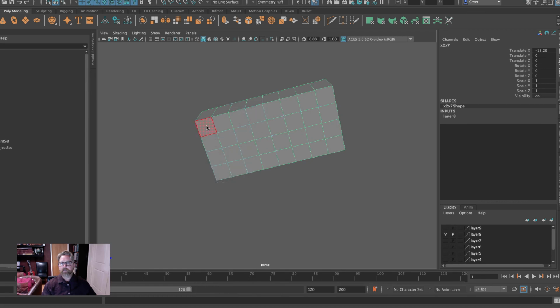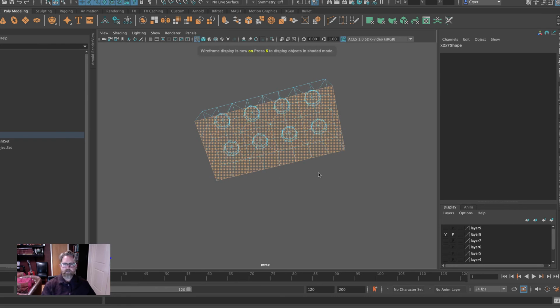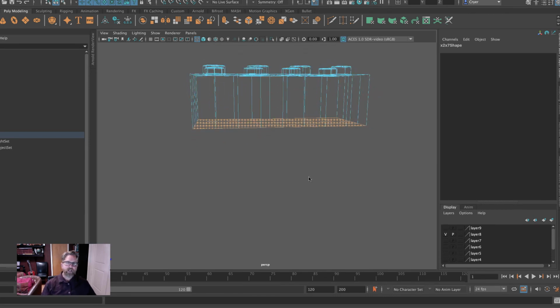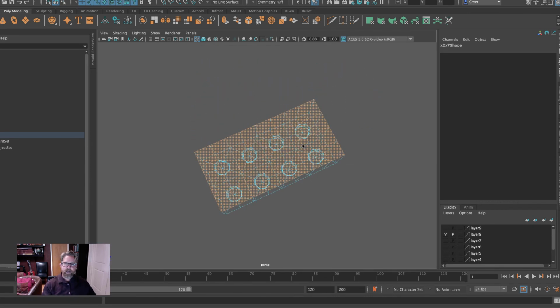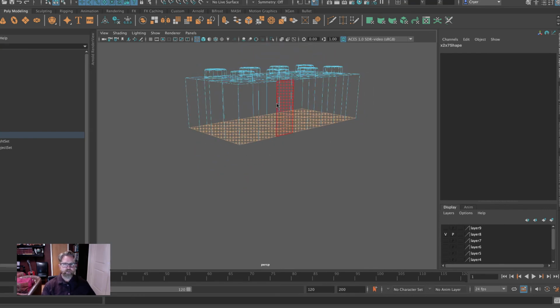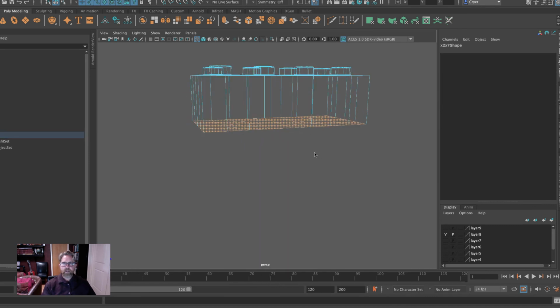We'll right click, we'll shift double click, shift double click, shift click, shift double click, shift click, shift double click. Hit the 4 key and you can see that you've got a clean selection. Another way to make that selection, the more faces you have, that probably wasn't the most practical way of making the selection. Let me just show you another way. We could right click to face, I'm going to click off, so we right click to face, I'll grab everything here.